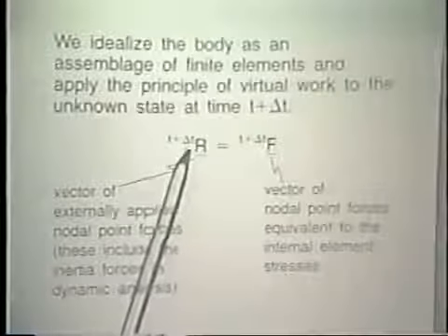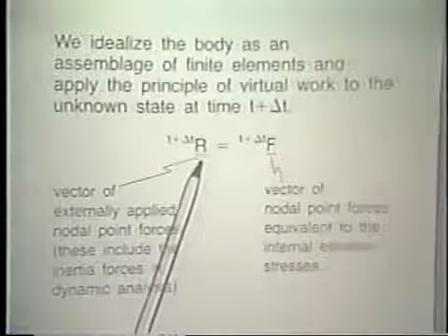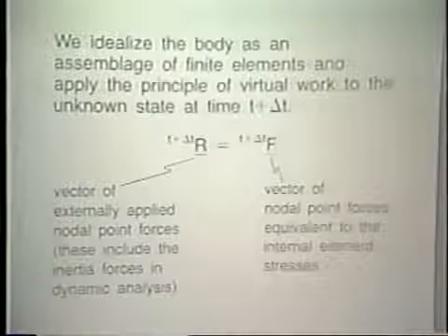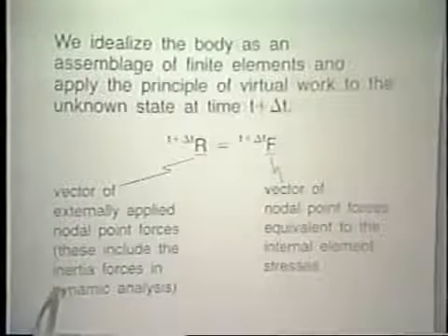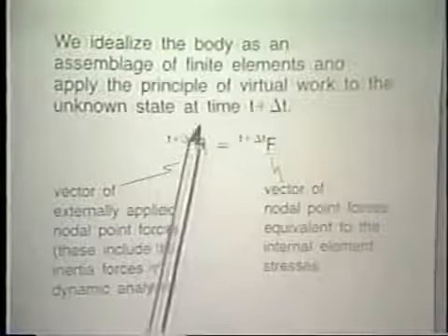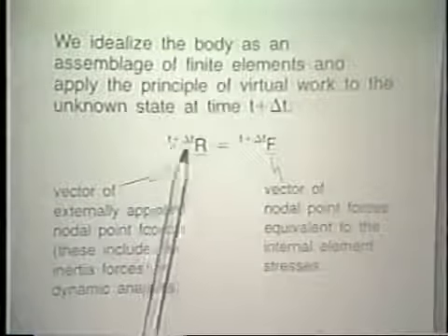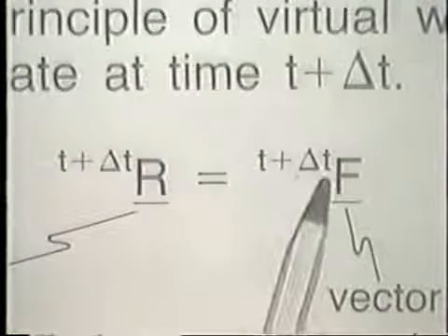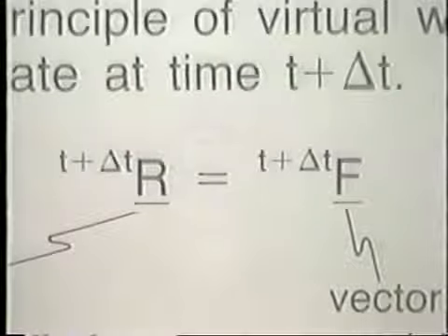We are saying that at any time step t plus delta t, the vector of externally applied loads, and this vector includes pressure loads, concentrated loads, and in the dynamic analysis also inertia forces, must be equal to the vector f at time t plus delta t, where this vector f corresponds to the internal element stresses at time t plus delta t.